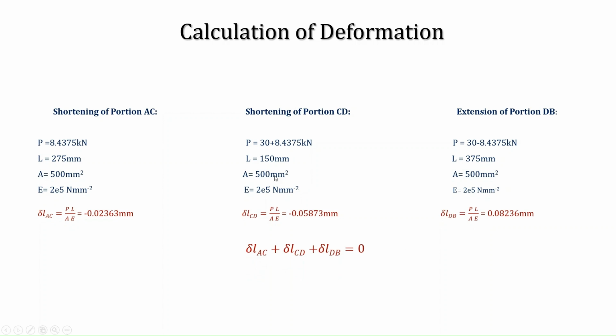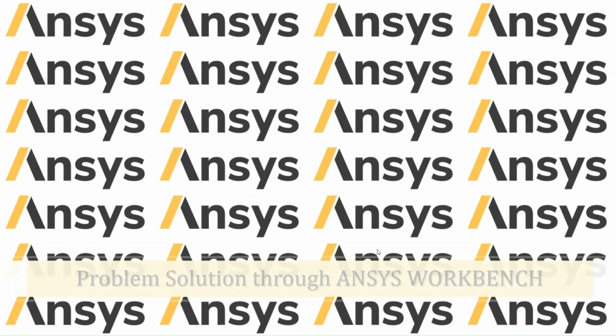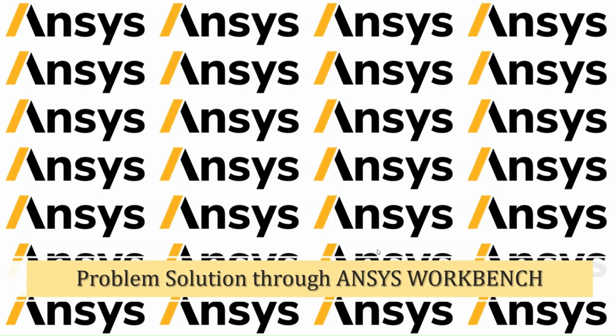So if you just add up the deformation from AC, CD, it is equal to DB with a negative sign. So negative and positive, they get cancelled, which is equal to 0. So this is the value of the deformation. So we have seen how to compute the reaction forces, stresses, and the deformation values using the strength of materials approach. Now let us see how to compute the parameters using the Ansys Workbench.